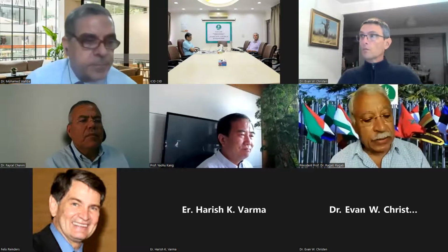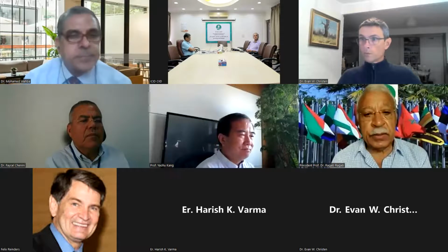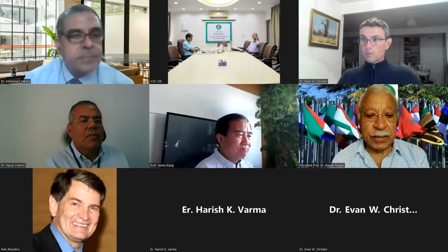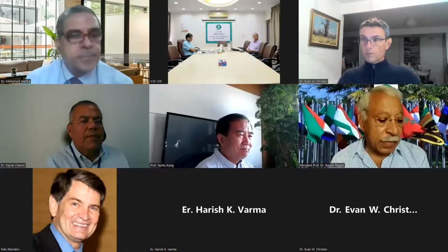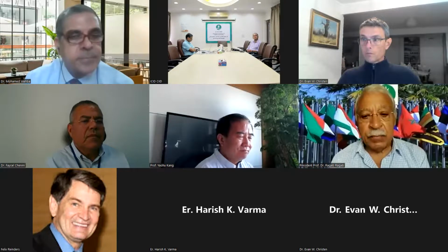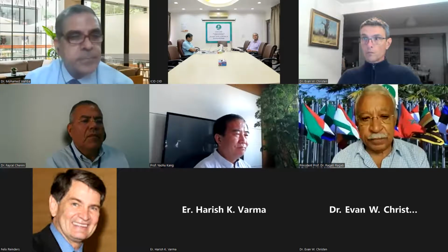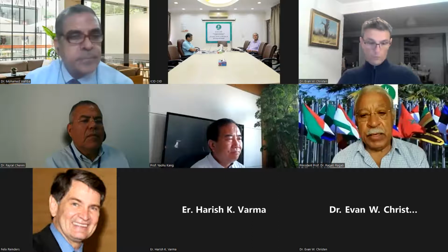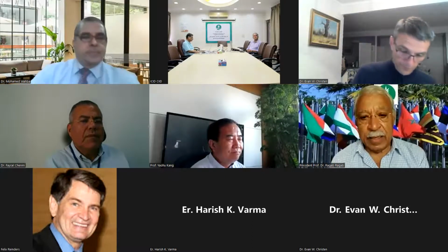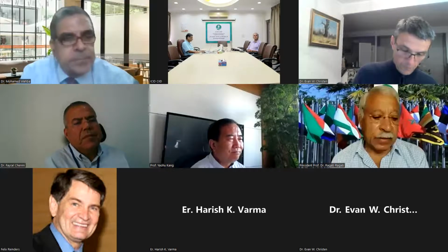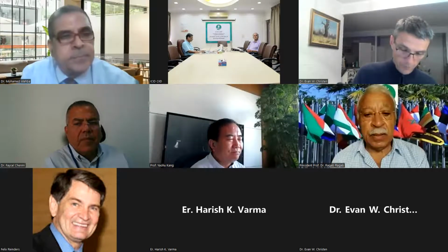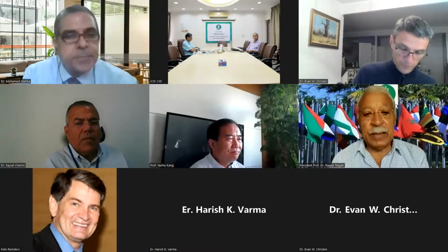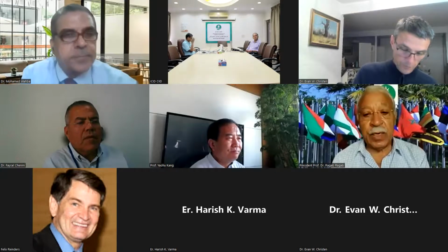But I have other comments on the excellent presentation of Professor Kang. He is always very rich in knowledge and experience, and we all learn from him. My experience in arid regions might be different from the experience in China. In arid regions, tensiometers fall beyond the maximum range most of the time. I tried that myself in Egypt, and I found it different from when I used tensiometers in the UK, because it is a humid, more rainy area. So tensiometers still work within the range.